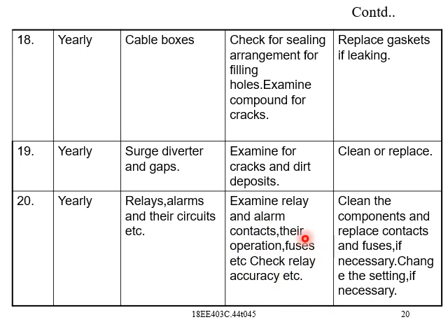And if any unsatisfactory condition is found, clean the components and replace the contacts and fuses if necessary, and change the settings if necessary. If any low grading settings are there, you can improve it by changing the settings.